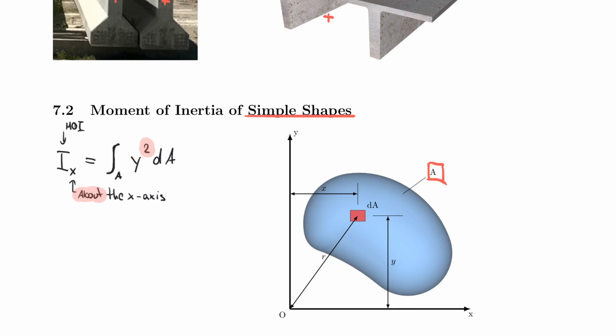And remember that before, when we talked about the moment of inertia, when we talked about the centroid location, right? I'll write that formula again. Centroid location was the sum of x tilde A_i, or actually let's talk about y tilde A_i, which then would make this here also y. So let's fix that. And then sum A_i.